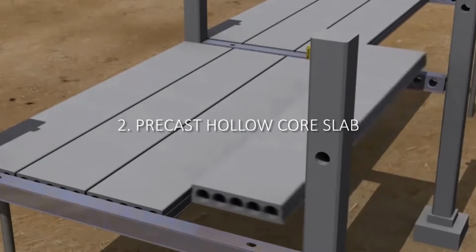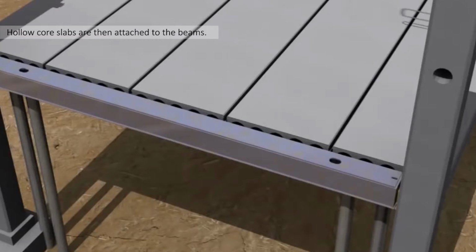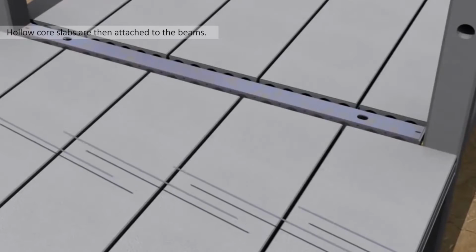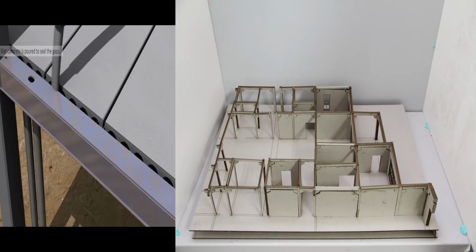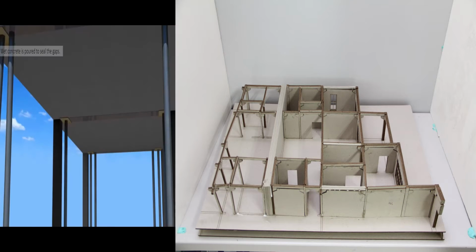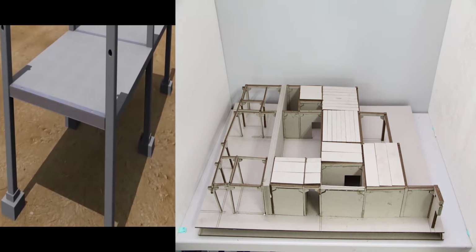After that, columns are installed and then followed by the wall on the ground floor. The precast wall is connected to the beam using steel plate. The plate is cast into the wall during precast process. Grout is filled at the bottom of the wall. After that, loose steel plate is welded to the cast in steel plate to make the wall straight and stable.